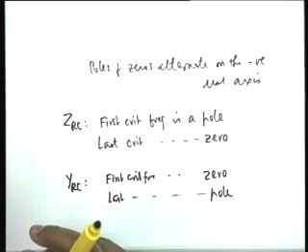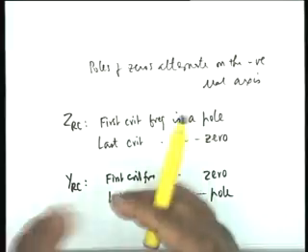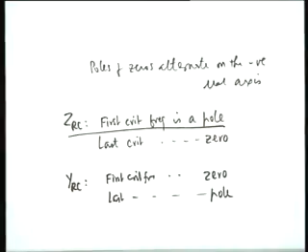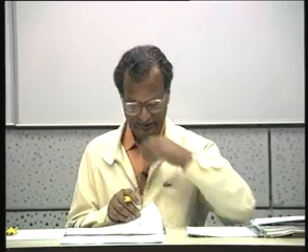If you remember that the first critical frequency of a ZRC is a pole, then you can remember everything else. If the first is a pole, the last has to be a 0, and for a YRC it is exactly the reverse. You remember just one of the statements, and I find it very convenient to remember that the first critical frequency is a pole. Now these peculiarities of the description of ZRC and YRC put a lot of restrictions on the synthesis.